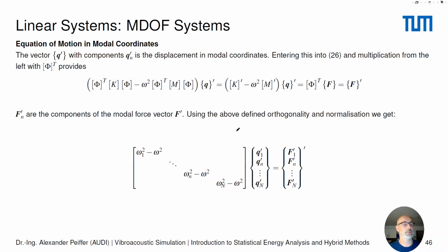Why is that? We just have the mass matrix multiplied by omega. These are all the omegas that we have here. And the K matrix leads to all the omega 1, omega n, and on the final and last used modal frequency. So our super complicated matrix is now downsized to a diagonal matrix. And this makes the solution very, very simple.